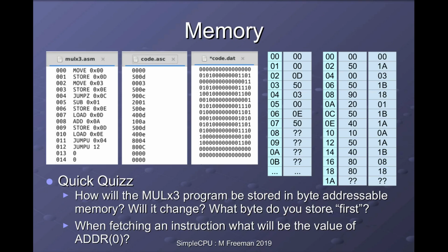So going back to considering how instructions are stored in memory, we can see that they have to be aligned to even address boundaries. So you can see instructions start at address 0, 2, 4, 6, 8 going through.